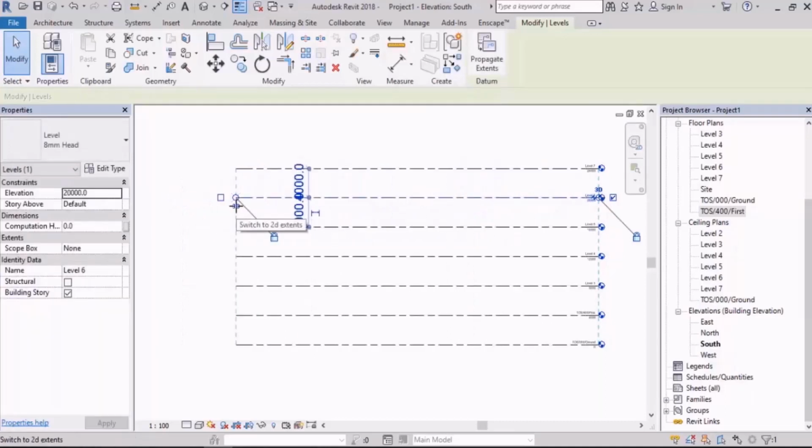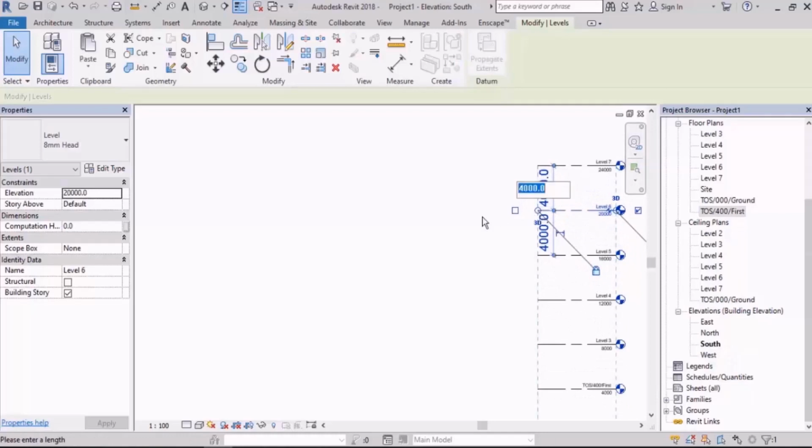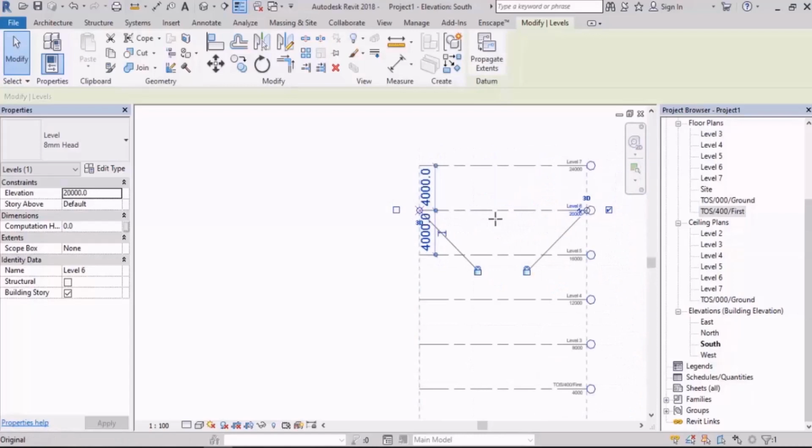Now, a very important point, a very important advice, never bunch your level lines like this and put it somewhere. It has to be like this, in this way, in your whole project. I know that maybe while you're printing you don't want them in your project, but I will explain that to you. I got that, but while working you shouldn't bunch them because when this happens, they might not be seen in some of the views. So remember not to do this.